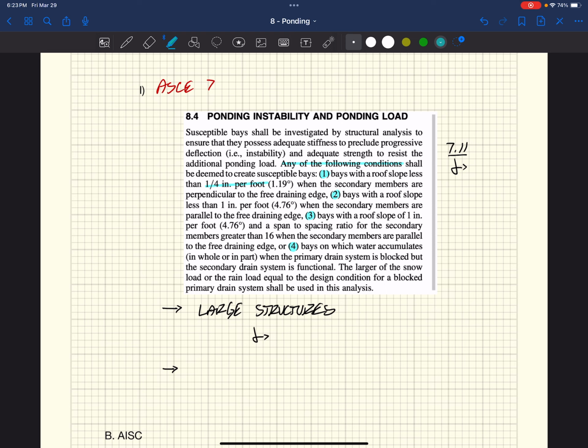So obviously snow is frozen water. So if we think about snow load as it relates to a pounds per square foot value, right? A 30 pound per square foot snow load would be equivalent to almost half a foot, right? If we think about 62.4 pounds per cubic foot for water density, and if we have 30 pounds per square foot, that's essentially saying we almost have half a foot of water sitting on our roof. And I will tell you that is a lot of water.